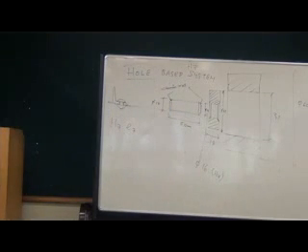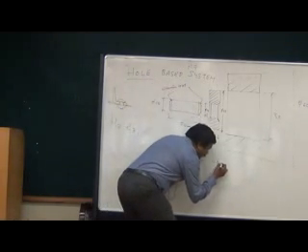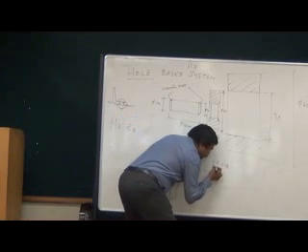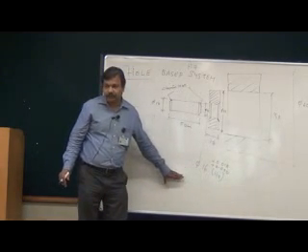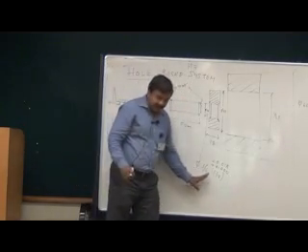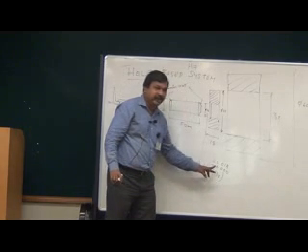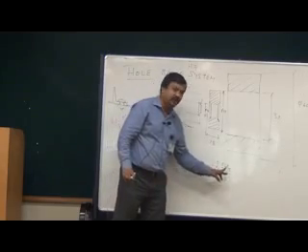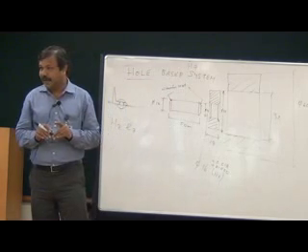H7 16 is plus 18, plus 0, that is plus 0.018 and 0. This is the hole dimension. So the hole will have a tolerance of 16 mm H7, meaning the diameter can be between 16 plus 0.000 and plus 0.018. Is it okay?